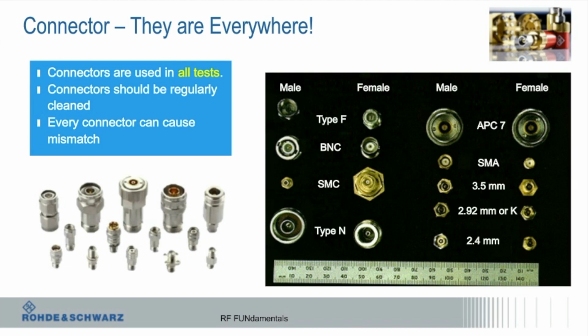BNC, I forget what the upper frequency spec is on BNC, but typically you look at reference signals, clock signals, a lot of the scope stuff. Is my scope brother in here? No. So I can make wise scope cracks. Anyway, scopes, until they got up into the microwave range, typically had BNCs on them, but typically not as the actual test connector. And you see here there are adapters, so you can go from one thing to another, but just be careful.